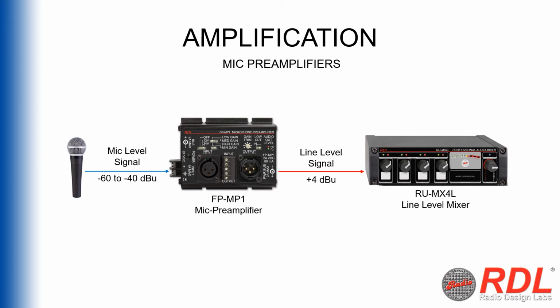They can be standalone devices or integrated into various electronics such as audio mixers and DSPs. They're available as a single channel unit or as multi-channel units that usually support either 2, 4, or 8 microphones. Preamplifiers can be designed to provide either a fixed or an adjustable amount of boost, typically in the range of 30 to 60 dB, where some units may boost higher.